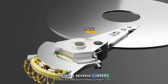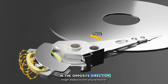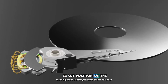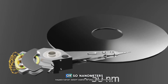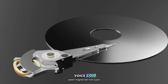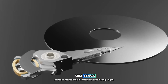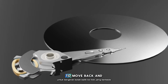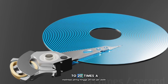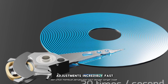When a reverse current is sent through the voice coil, the arm is forced in the opposite direction, thereby enabling control of the exact position of the read-write head within 30 or so nanometers. Additionally, the magnet and voice coil make a rather strong motor that enable the lightweight arm stack assembly and read-write head to move back and forth to different tracks across the platter, up to 20 times a second, and to make small adjustments incredibly fast.